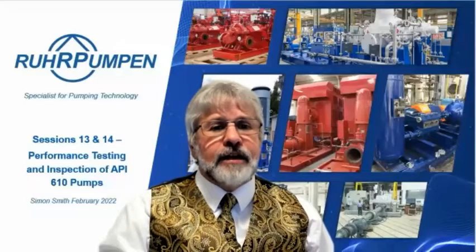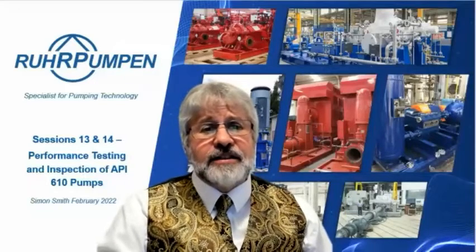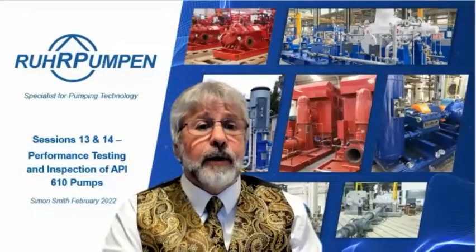Should I seal test after performance testing? Well, the performance test has a mechanical seal test. The mechanical seal is fitted when you do the performance test, so you've got a functional test of the mechanical seal anyway.